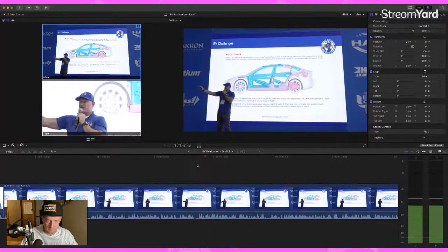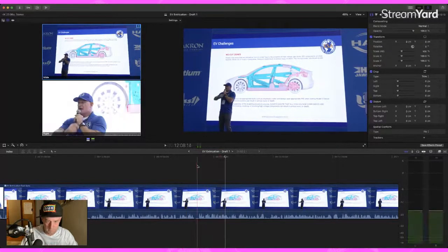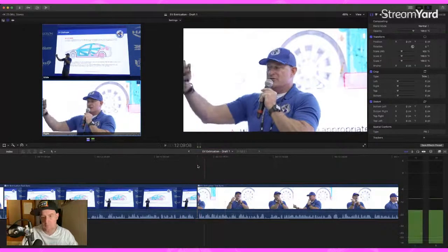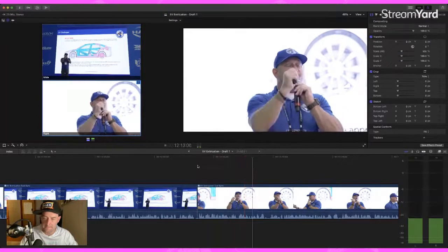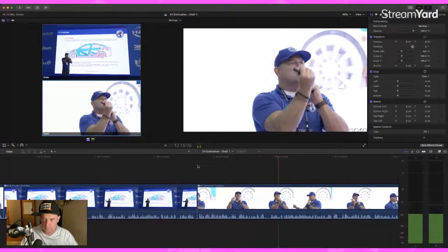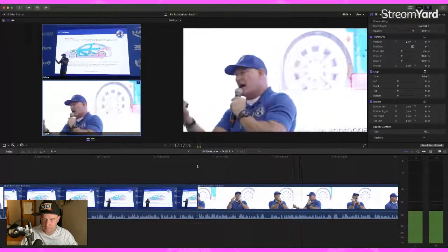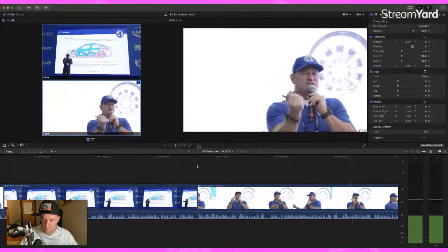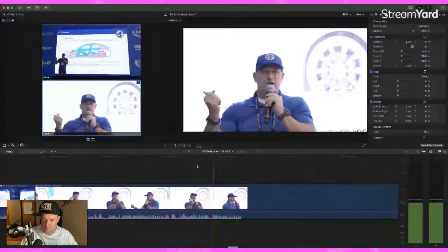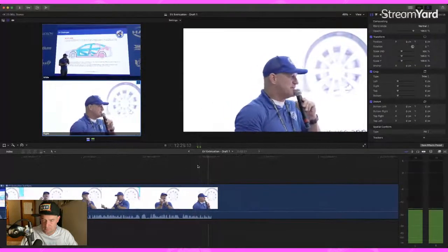But when you damage elements of a vehicle in a high-speed collision, a lot of those safety features don't work. So you may expect the vehicle to be isolated or automated in a shutdown procedure, and it's not, all right? So always assume the vehicles are energized when you are engaging them as extrication personnel.